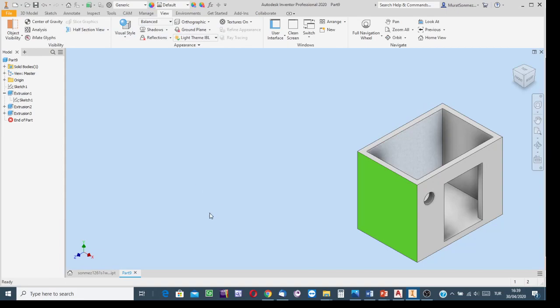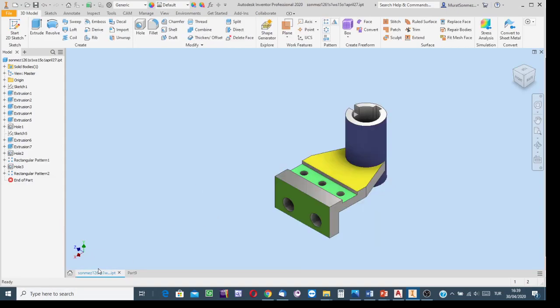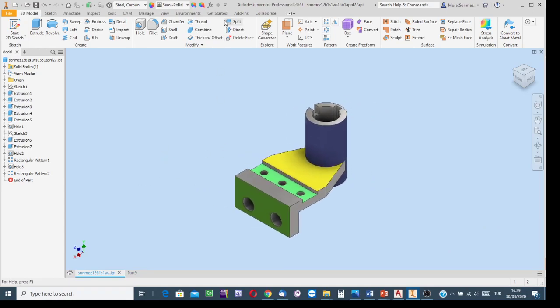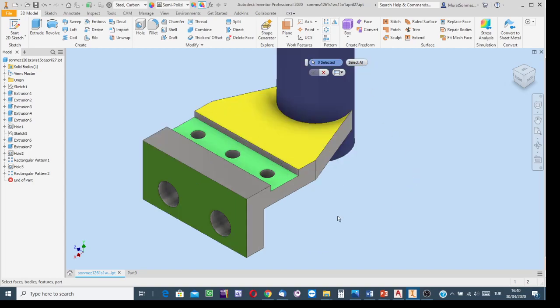Okay, then in Inventor, these are, I think, all understandable. How the surface is painted. To remove surface paint, what is the procedure? Say remove the dyes from surfaces. Click on this button and then select all if you're going to remove all the dyes. But if you're going to remove paint from one or a few surfaces only, indicate the surface and then click on the OK button. Then from the indicated surface, the paint will be removed. If you select the all surfaces option in this dialog, then after clicking on this button, dye will be removed from all the surfaces.